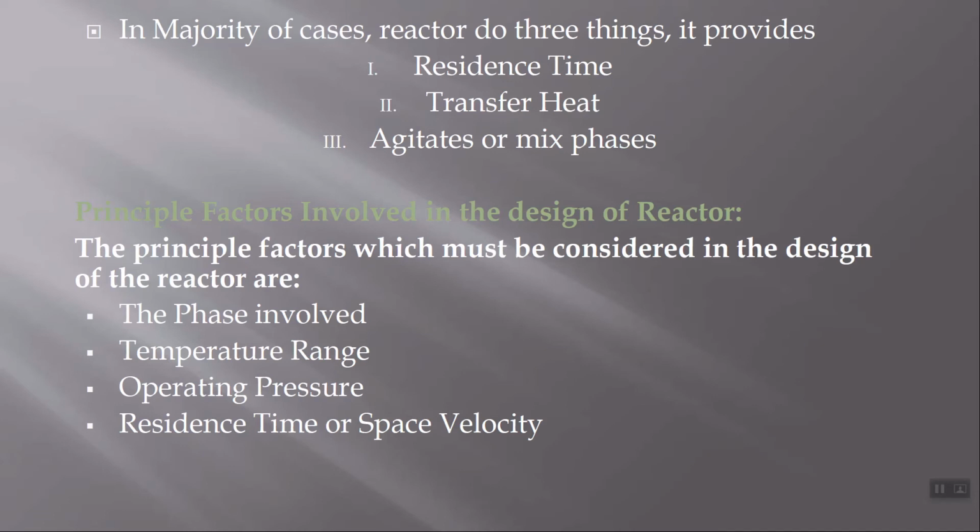The principal factor which must be considered in the design of the reactors is the phases involved. As I mentioned, we must know which phases are reacting in the reactor. Do we have gases? Do we have liquids or even solids? Maybe the catalysts are solid parts of many reactions.